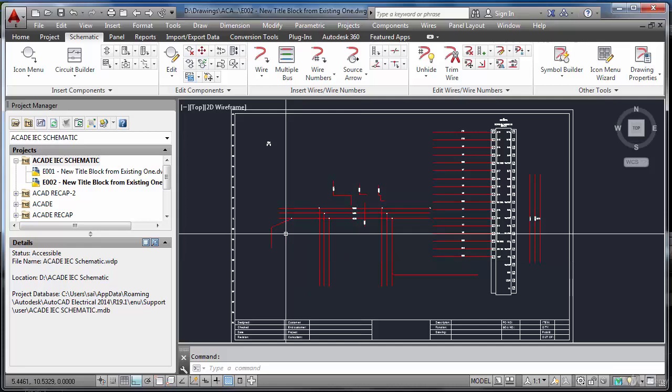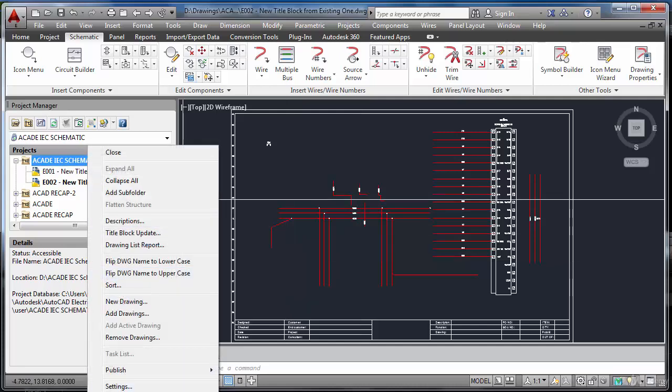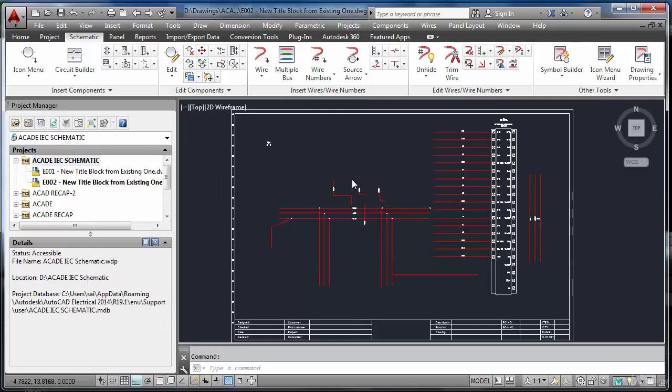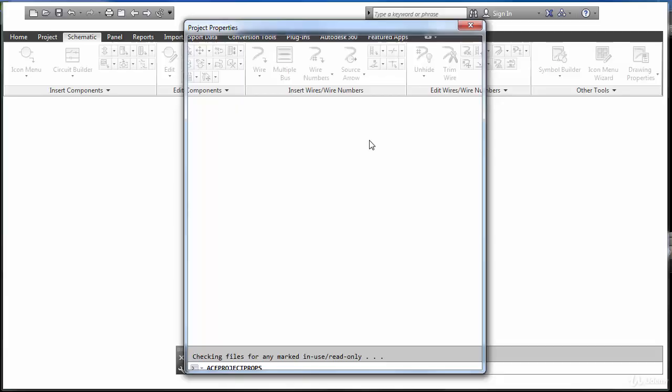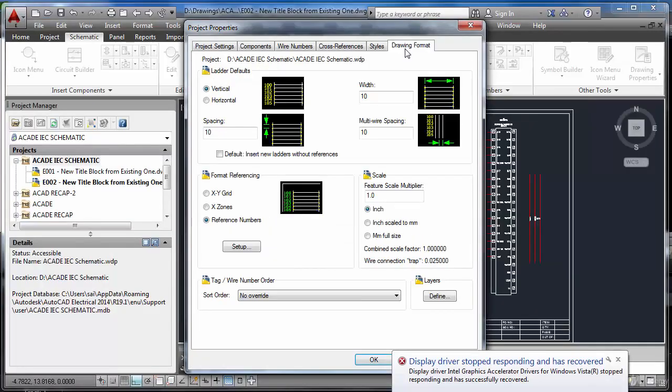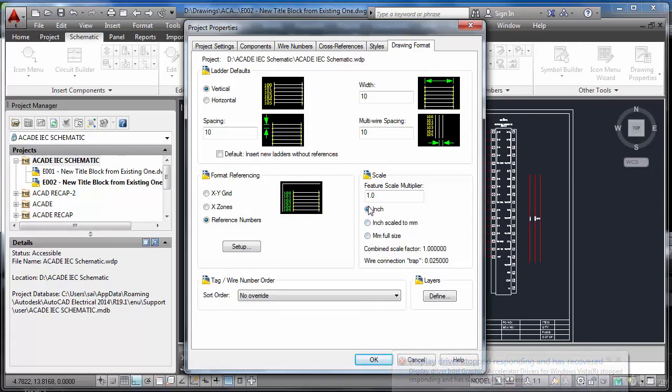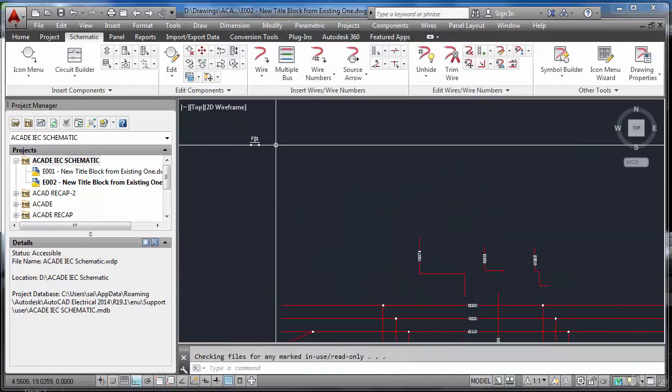So in that case, make sure inside the properties, here inside the properties, see, full scale, you should set this scale. Now it is in inches, so fine. If you are using metric, make it full scale. Fine. This is how you can insert.